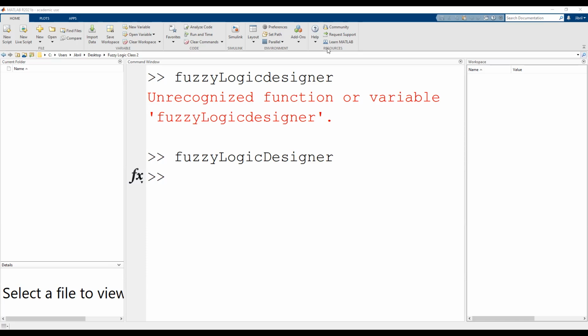If you remember from the theory class, the basic component of a fuzzy system is you have the input from the real world, which is the crisp input that comes into the system. And when that input comes into the system, you have to convert it to a fuzzy input, so that the inference inside can use the rules to determine what kind of output you get from that input. That conversion of the crisp input to the fuzzy input is called fuzzification. And we mostly use membership functions for that.